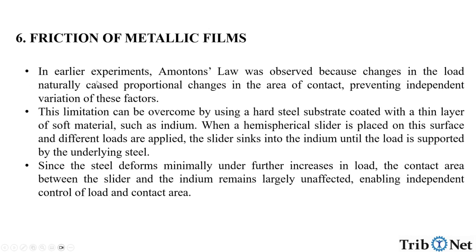Friction of metallic films. In the earlier experiments, Amontons' law was observed because changes in the load naturally cause proportional changes in the area of contact, preventing independent variation of these factors. This limitation can be overcome by using a hard steel substrate coated with a thin layer of soft material such as indium. When a hemispherical slider is placed on this surface and different loads are applied, the slider sinks into the indium until the load is supported by the underlying steel. Since the steel deforms minimally, under further increase in load, the contact area between the slider and the indium remains largely unaffected, enabling independent control of the load and contact area.